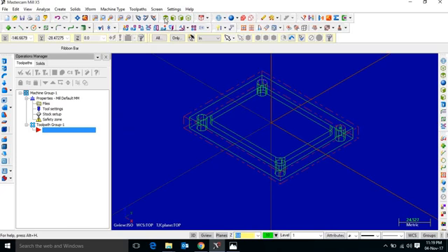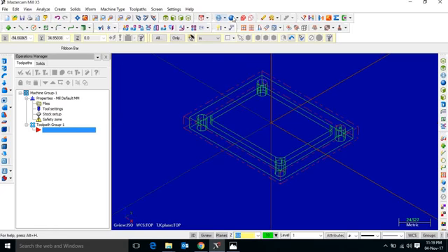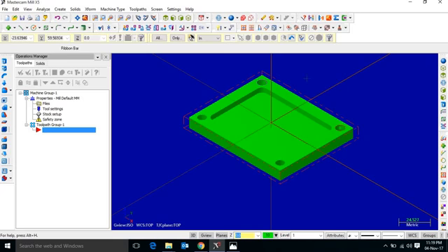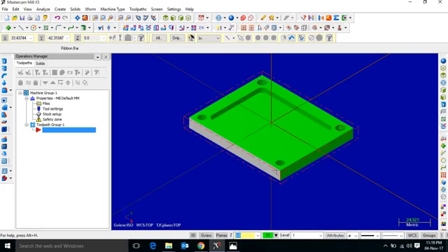Wireframe, again you are using the wireframe, top view. Now there are some operations in milling. We can first see them one by one. First, we do the facing operation. 1 mm facing is done because in the problem statement there is a 10 mm job profile, but we selected 11 mm raw material, so we need to remove the 1 mm of raw material.